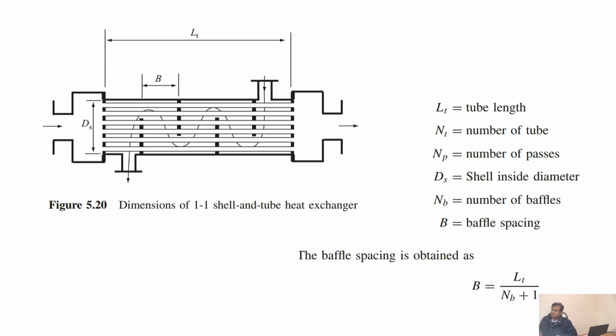So to calculate heat transfer coefficient, you need things like velocities, and you need to be able to calculate Reynolds number, so you know whether it's laminar flow or turbulent flow. Then you have to make a judgment as to whether it can be entry length flow or fully developed flow. Okay, you need all these things because then you will be able to identify some correlations which are applicable. Ultimately in heat transfer, whatever you learned in undergraduate, it comes down to some correlations, right? Finally, and then you get HI, then you get HO.